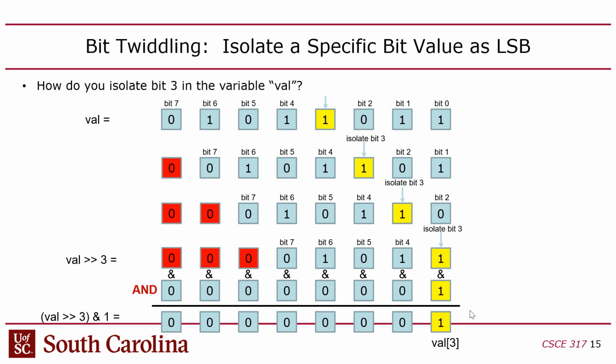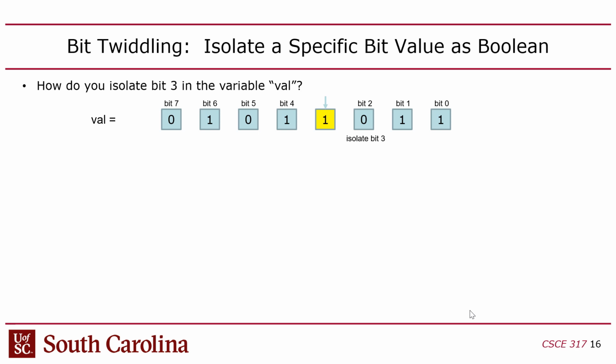And you might say, well, why do you want it in bit 0? Well, because it should be right justified, right? And also, by doing that, I can just do a bitwise AND with the value 1, and it will isolate that specific bit, right? So basically, shift 3 bits to the right, and with 1, and that'll just leave me with 1 bit, whatever the original bit 3 was, all by itself in the register and all the way to the right-hand side, so it will be properly aligned in the value, right?